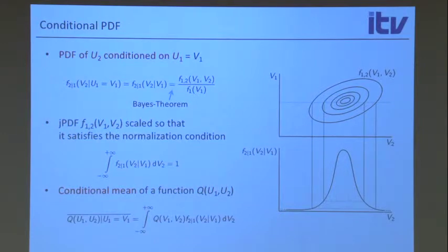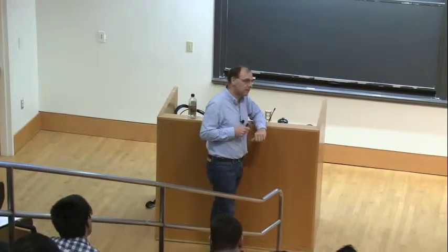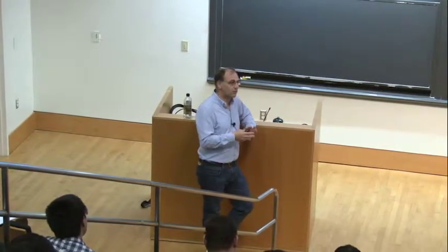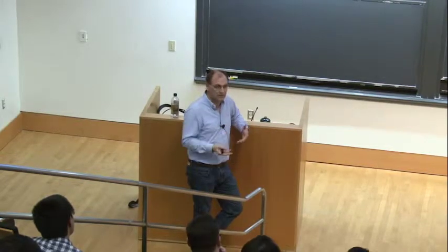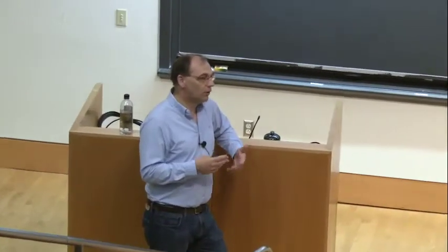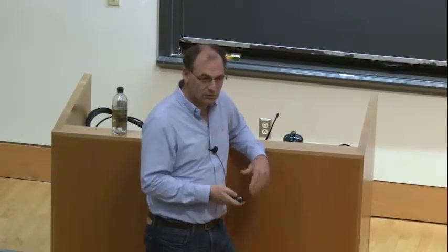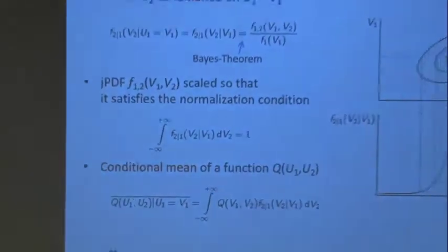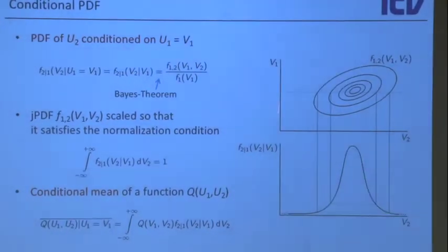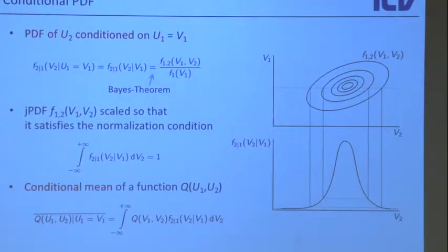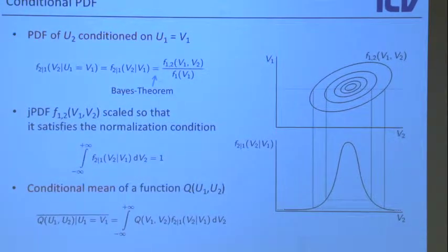Of course, you know that one-dimensional simulation is simple. Here, use this Flame Master code. It's fast, it's simple, everything easy. If you want to solve chemistry in two dimensions, that's a little more complicated already. Solving things in three dimensions, maybe a DNS or LES, can be very, very costly. Here, we're talking about something that we want to solve in four dimensions. Now, if you have a joint PDF of V1 and V2, we're talking about five dimensions. You have to discretize this in a five-dimensional space.